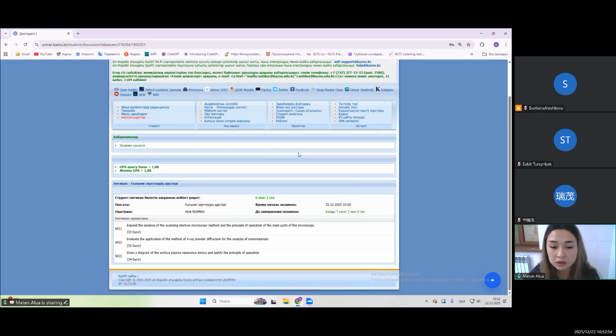Secondary electrons provide detailed information about surface topography. Backscattered electrons give contrast related to atomic number difference. The detectors collect these signals and convert them into electrical signals, which produce the high resolution image. SEM enables detailed visualization of surface features.